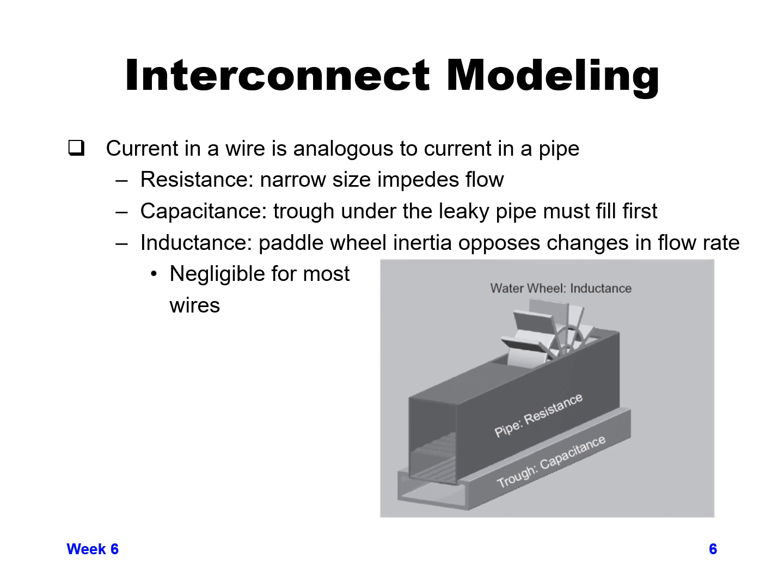Now, for most wires in an integrated circuit that are internal to your design, inductance is usually ignored for virtually all wires. Some exceptions would include I/O, things that are going off chip, so signals that you're sending off chip, and also your power network. So VCC and VSS tend to have some inductance that winds up getting modeled, but most of your wires internal to your design, you pretty much ignore inductance for internal wiring.